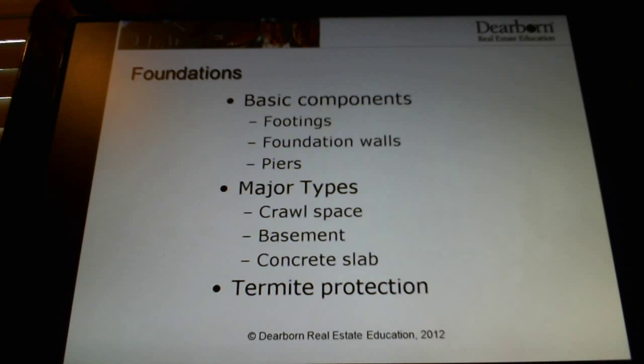Dealing with termites is simply a matter of inspecting, and when you find them, get rid of them early on before they have a chance to do a lot of damage. So there definitely are going to be times when you have inspections on properties, and we usually don't call it a termite inspection anymore. We call it a wood-destroying insect inspection, and you're going to find them. They are attracted to humid environments. They love pine wood, which is what most homes are built out of in North Carolina, and obviously we have humid environments, and the more moisture is present, the more likely you are to find termites.